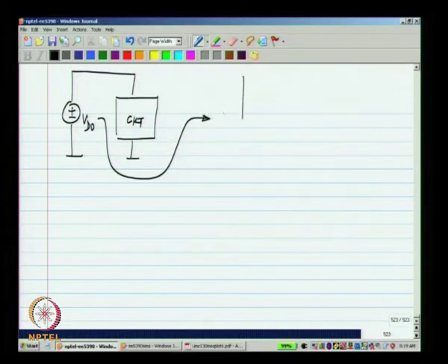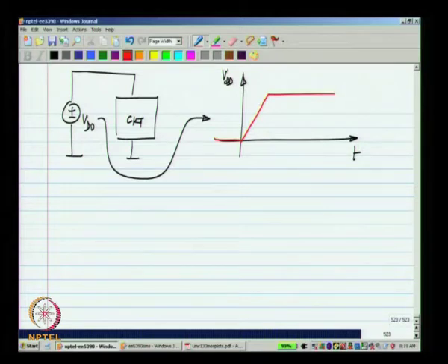So, for that what is normally done is, the supply voltage is stepped up or ramped up at a certain rate from 0 to its value, whatever it is, let us say 3.3 volts, and then you examine what happens in the circuit to see that everything comes up. Now, this is again a non-trivial thing, because of non-linearity and complicated feedback loops.